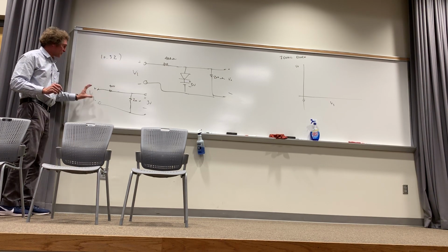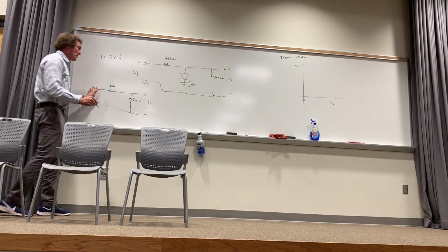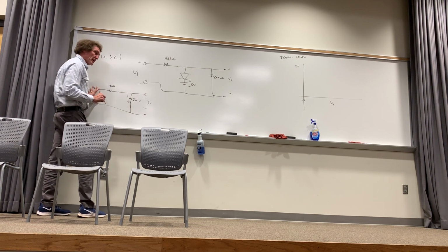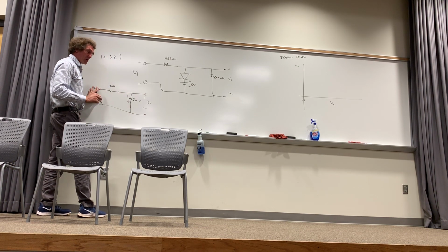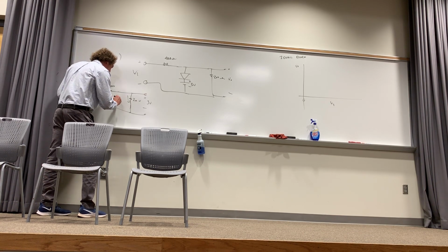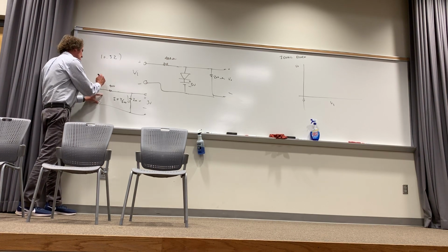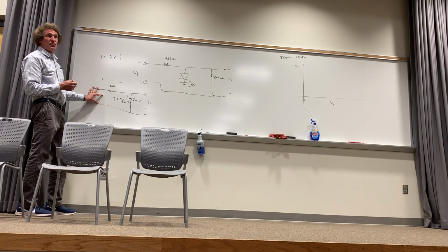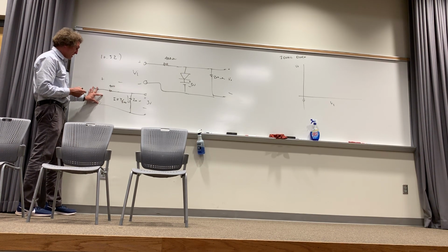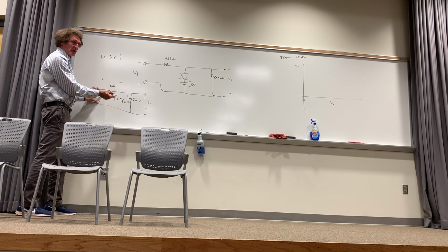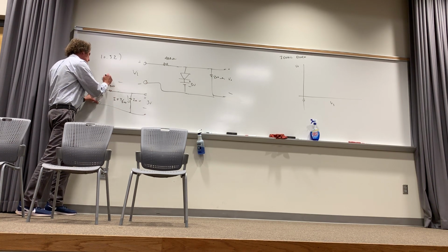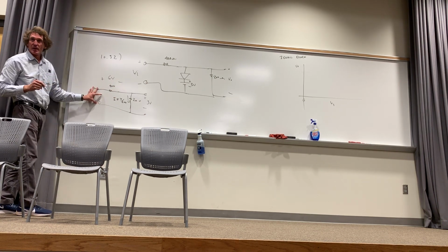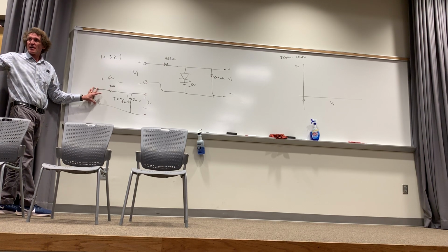So what does that mean for this voltage? Well, if 3 volts there, what's the current flowing here? 3 over 200, right? So the current I would be 3 over 200, right? And what would the voltage here be? 3 over 200 times 400, right? If that's 400 ohms. Or it's really 3 times 2, right? Or 6 volts. Do you agree with me there, class? Everybody with me on this?